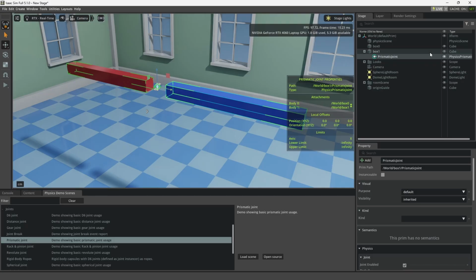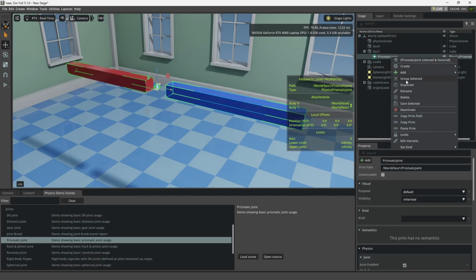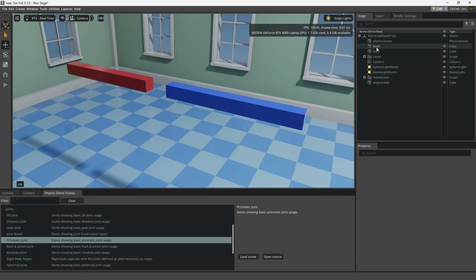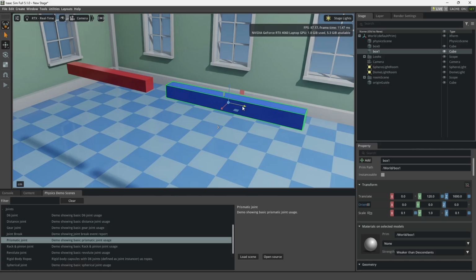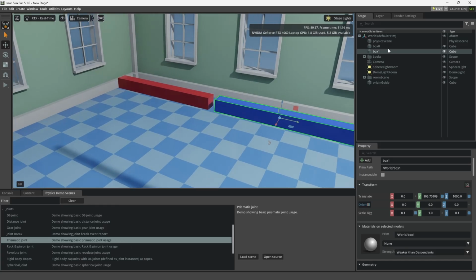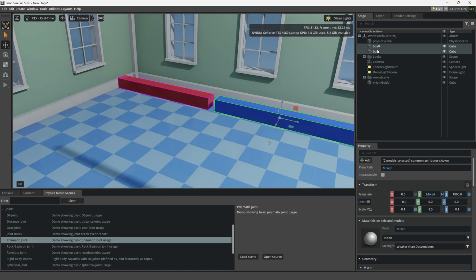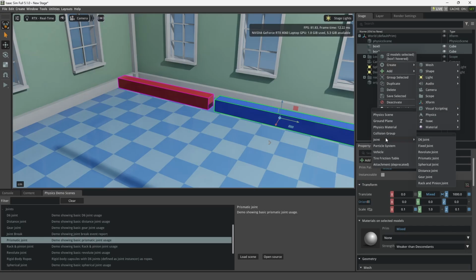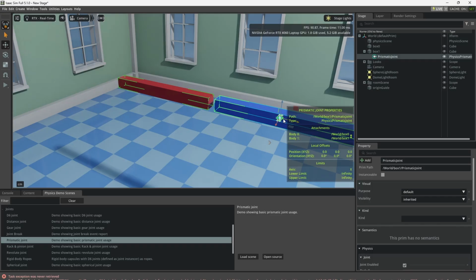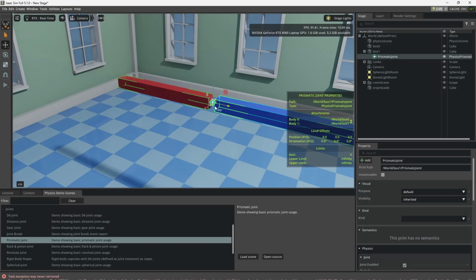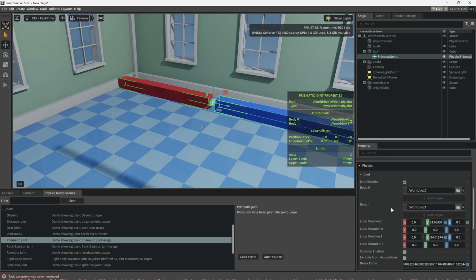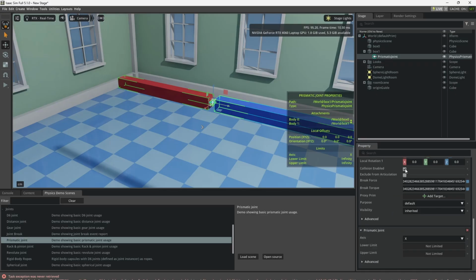And you can see it makes it a lot easier when you're actually, let's do that. Let's delete this joint again, because I was getting distracted by the fact that what if I wanted box 1 closer? If I knew that I wanted it closer, we would just basically start off with it that way, so that when we create our new joint by control clicking box 1, hit create, physics, joint, prismatic joint.